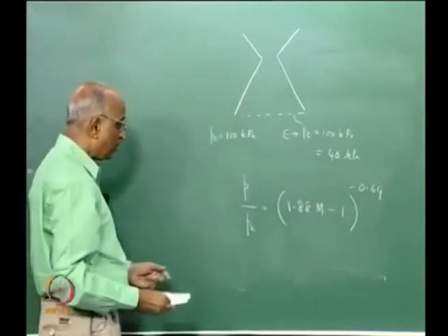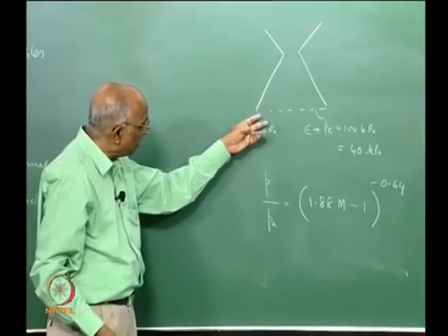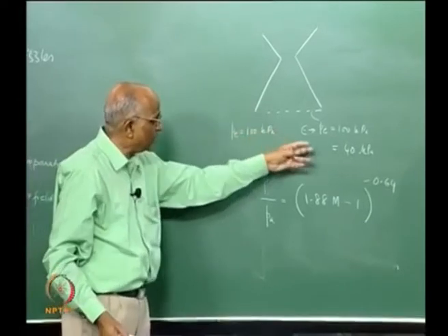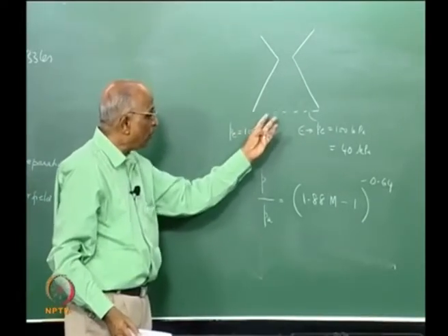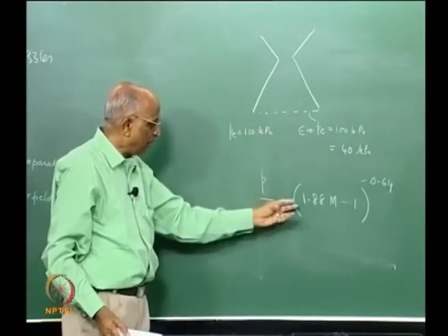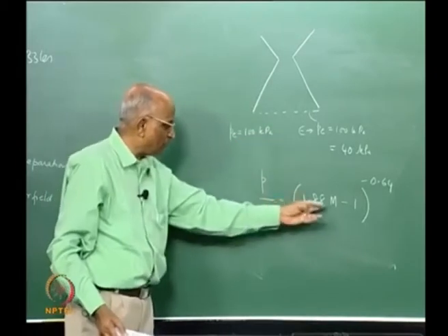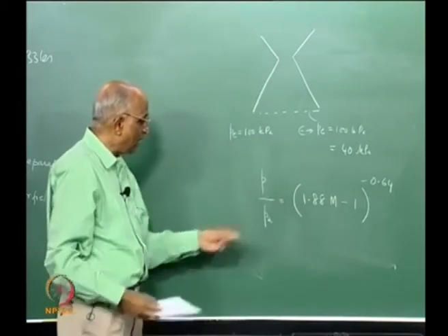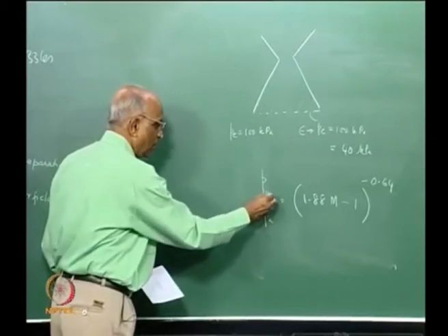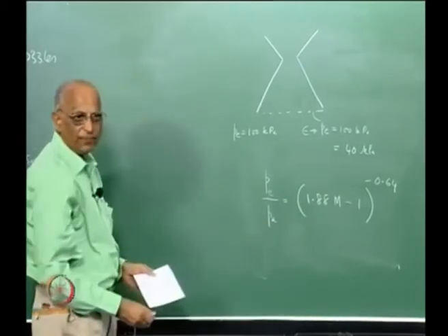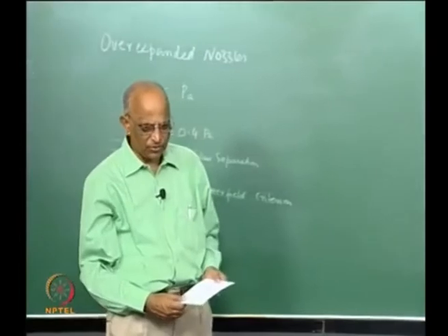In fact, based on experiments, it is not only the inertial force which delays it to a constant value of 0.4 times the ambient pressure, but it depends on the local Mach number at which flow separation takes place, and this is the value of the exit pressure for which flow separation takes place. This is again based on experiments.